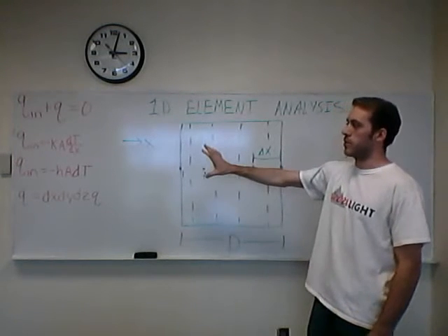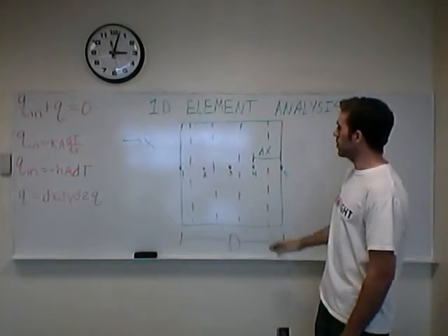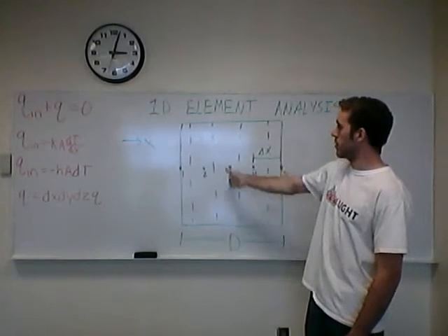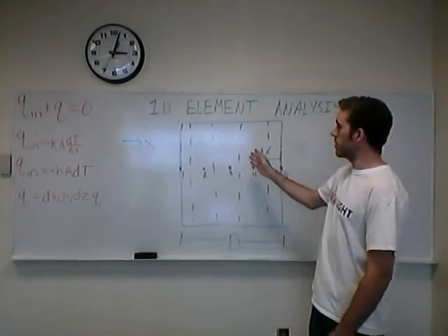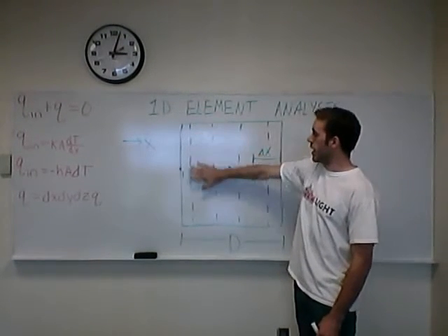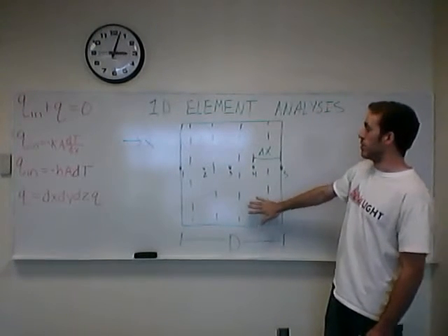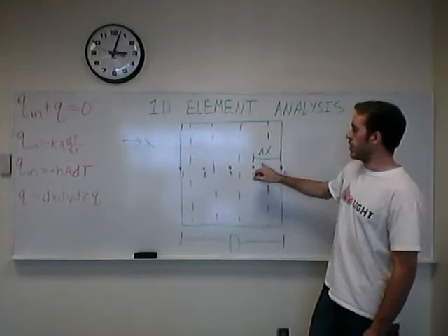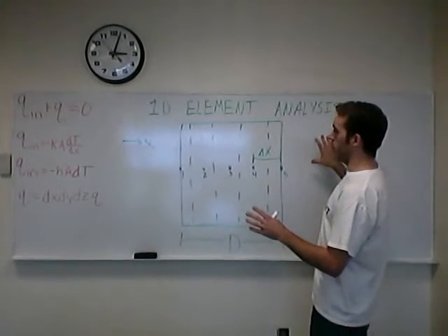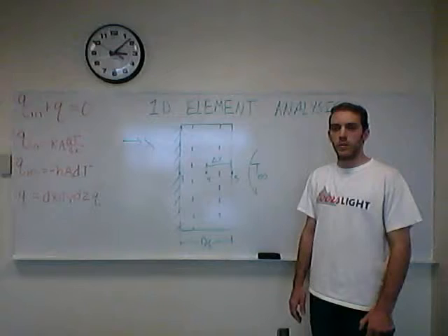Before analyzing and writing down equations using our thermal conductivity, you can notice that in your part, the elements are symmetrical about the center at node 3. This is important because you can get rid of half of your part because everything will be symmetrical. Whatever these temperatures come out to be will be the same on the opposite side. This is only true, however, if the boundary temperatures on each side of your part are the same.